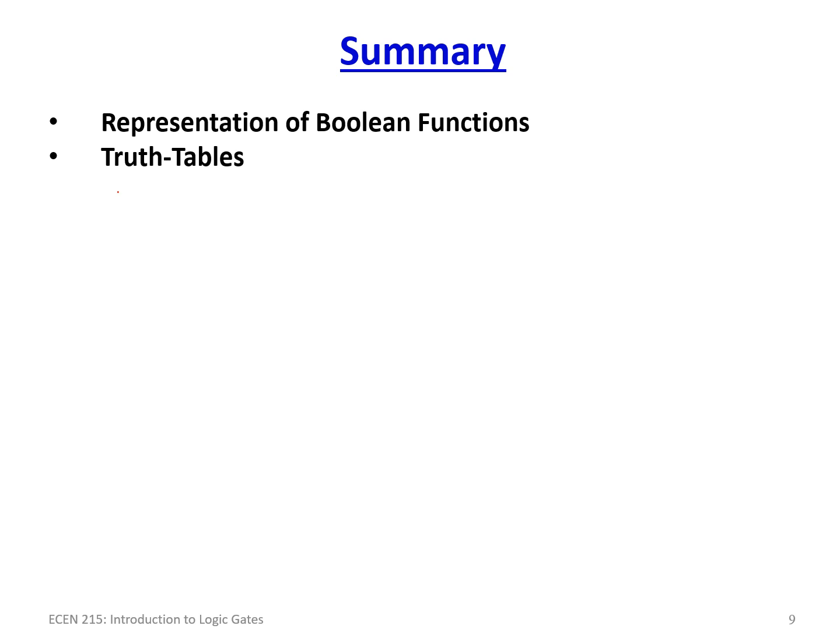So use truth tables to represent all the possible outcomes, and also how you're able to take a truth table and produce a Boolean function sum of products from that. That's very important to know how to do, by just simply looking at where F becomes 1 and combining the sum of products. In the earlier example where we had A, B, and C, and we had everything greater than or equal to 5, that is how we combined that.